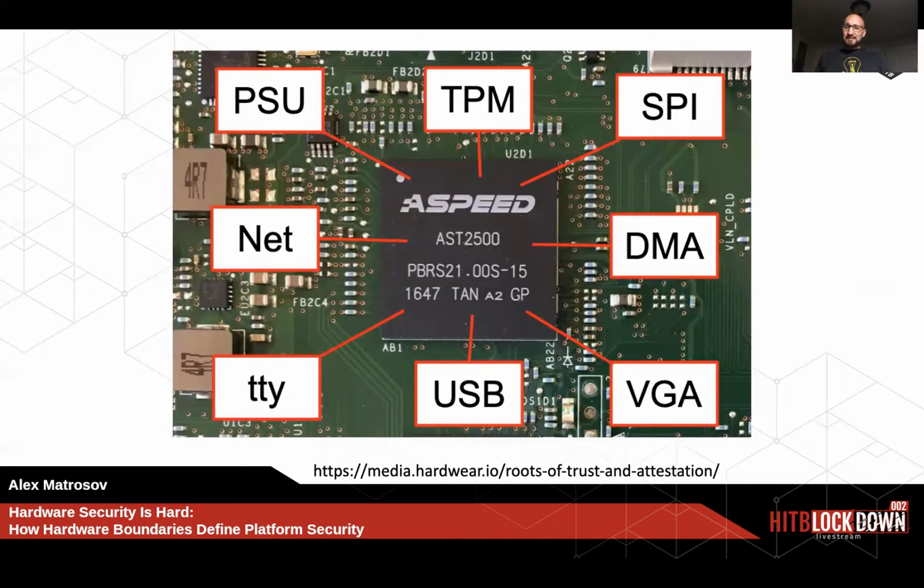Let's get back to the BMC. The BMC can actually update the firmware for most of the devices across the board. Even more, it can update the TPM and has infinite control over the SPI flash controller. It has a separate network interface, not dependent on the system board interface provided for the operating system and others. It's just separated for functional purposes.